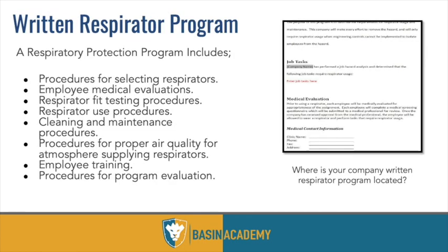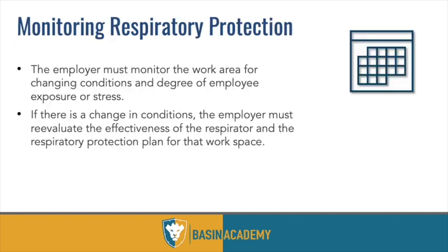So a written respirator program is another requirement for employers. Basically it needs to outline when you need to wear a respirator, how many parts per million, which it needs to be at minimum 100. It may be less though, maybe 50. I don't know. Your program may say something different. It also talks about change out schedules for PPE. Does each individual get their own respirator? Do we share respirators? Like, what's the plan? These are all the things that are going to be discussed in your respiratory protection plan. And again, it must meet the requirements of 1910.134.